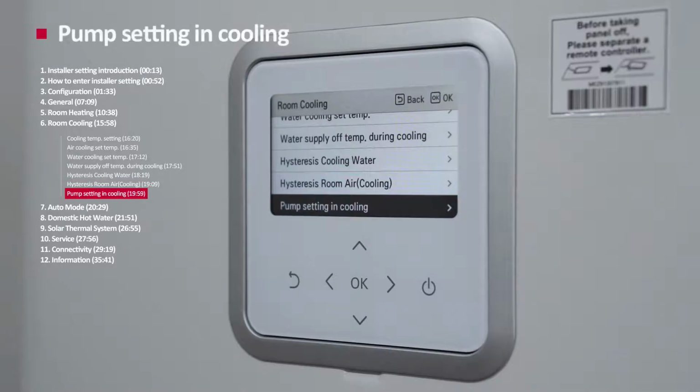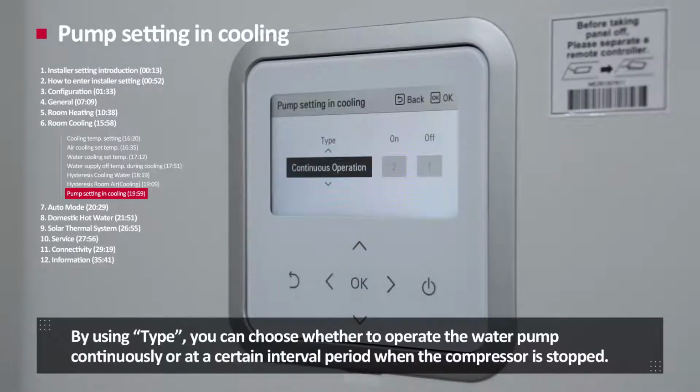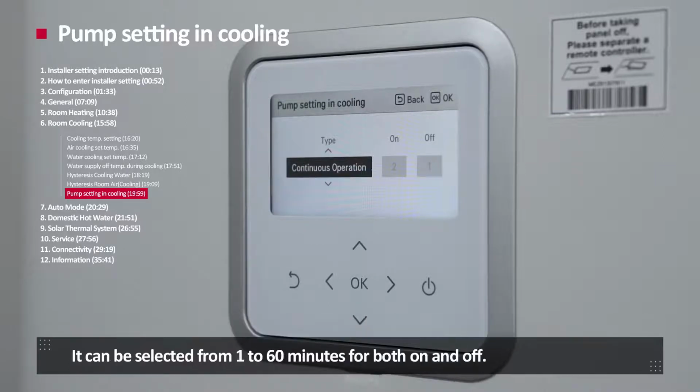Pump setting in cooling. It is to determine how to operate the water pump when the compressor is stopped in cooling mode. By using type, you can choose whether to operate the water pump continuously or at a certain interval period when the compressor is stopped. On means the duration of pump running time, and off means a duration of pump stop time. It can be selected from 1 to 60 minutes for both on and off.